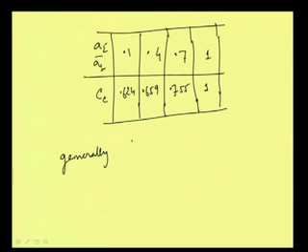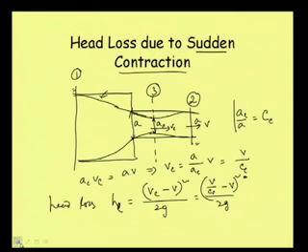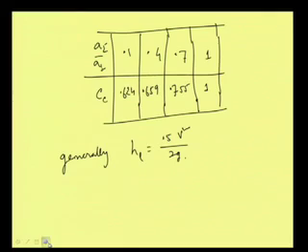So, generally this head loss HL due to contraction is taken as equal to, say, 0.5 V square by twice g, where V is the velocity. That means indirectly, if we put the Cc value, we will ultimately get this in terms of V square by twice g, and of course some other term, twice V1 V2, will also become V square with some coefficient. Putting those values, we get nearly this expression, and the value can be approximated as 0.5 V square by twice g.